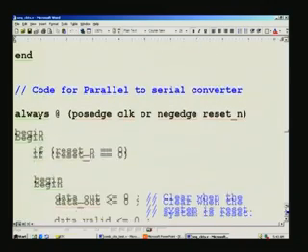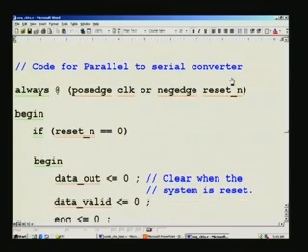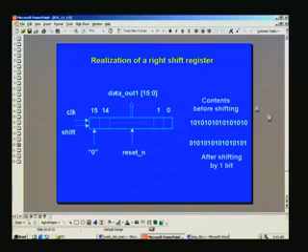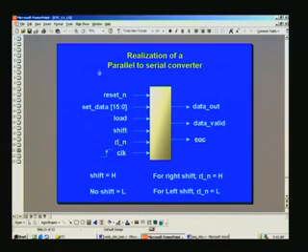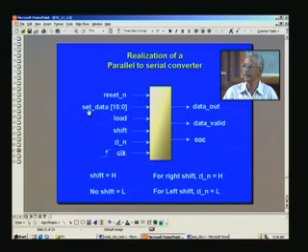And next we had taken was the parallel to serial converter, and this is what we had in the parallel to serial converter. We have a power on reset or system reset, and whatever value you want to serialize, you have parallel information that can be entered into a shift register inside this box through a 16-bit data bus. So whatever data you want to serialize and send out, you can load through this, provided you assert a load input as such.